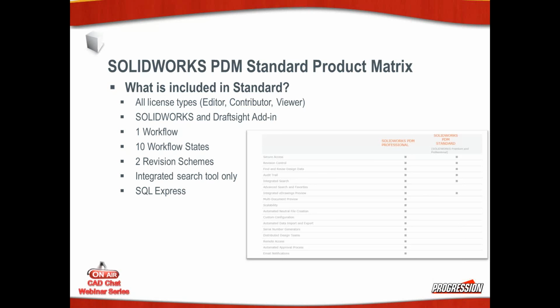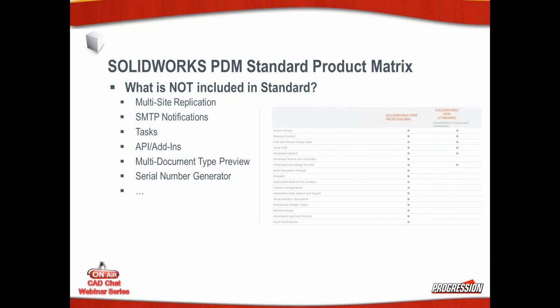It is limited to one workflow only, 10 workflow states within that workflow. It's also limited to 2 revision schemes. You can have an alpha and a numeric, for instance. It's got integrated search tool only, so there's no standalone separate window search tool as you have with the Professional package. And another big difference is, of course, it uses SQL Express, not the SQL Standard product. SQL Express is a free product. It's installed as part of the installation with the PDM Standard.